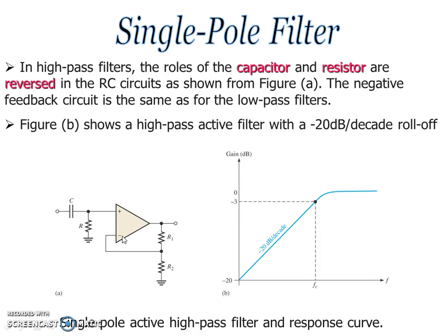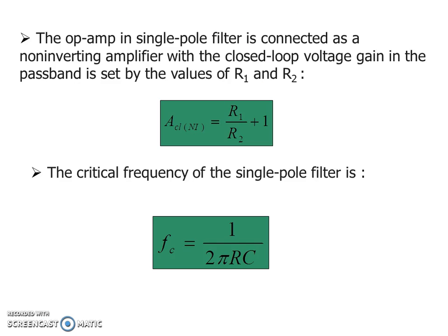So this is the circuit arrangement for a high pass filter, and we know that the gain roll off rate will be minus 20 dB per decade. One combination of R and C will provide one particular pole. So if you use these R and C components, we will have this particular pole here. You can change the order of the filter and obtain the number of poles. If you use an operational amplifier, you can vary the gain.